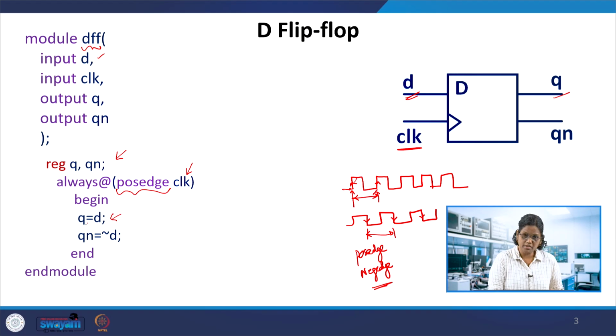So this is an immediate assignment, that we need to say the blocking assignment. We are doing the flip flop with the blocking assignment, but we'll also proceed with the non-blocking statements as well. So tilde D and Qn. So the Qn is getting the complement of this D here. Okay, so at the posedge of the clock.